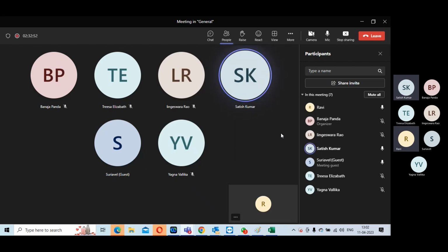In one of my blogs, I saw that in base layer DRC, because of the tap cell, it's not present because the row orientation is changed in a netlist. It should be in R0 and R90 in layer orientation, but it was reversed. So I'm getting around 5 lakh DRCs in base layer.